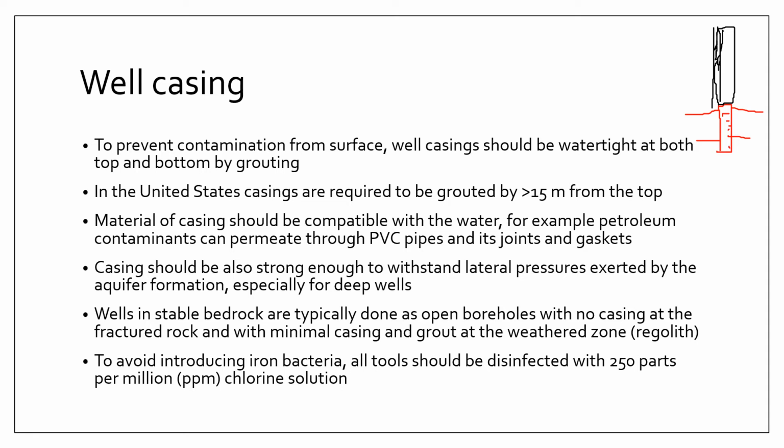So this is typically grouted or cemented to ensure that no surface water can enter your well from other points. So this is to ensure that the only water getting in your well is coming from your aquifer.